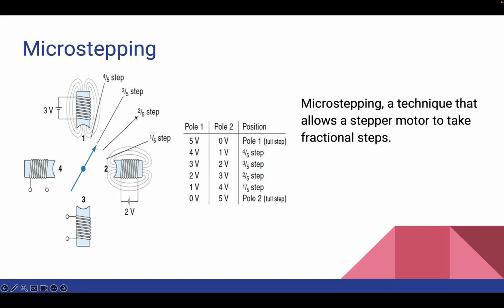So, when the motor takes a full step, there is a vibration shock you might have seen when you used motors in your laboratory experiments. But with microstepping, you will see smoother motion because of these tiny microsteps, which overall contributes to improved precision and overall system stability.